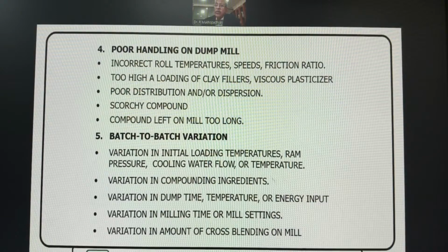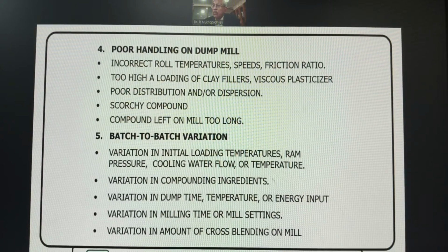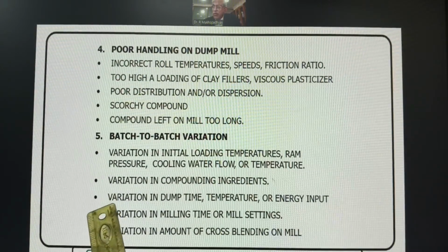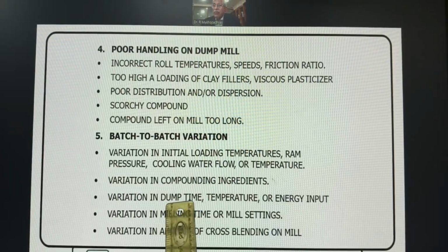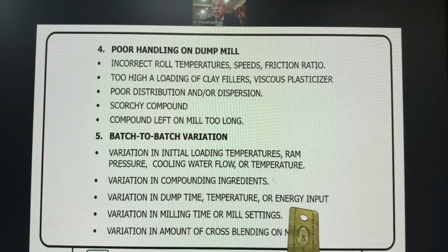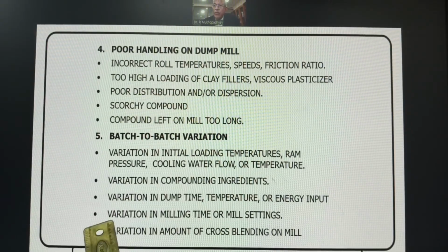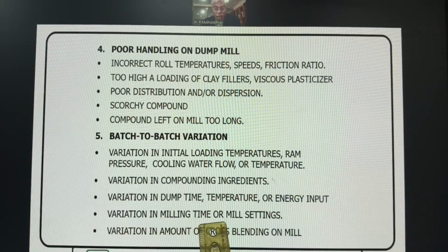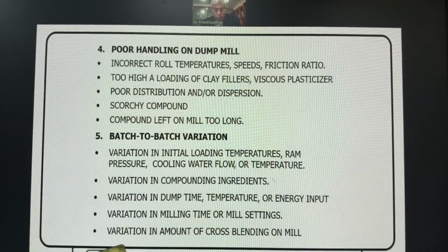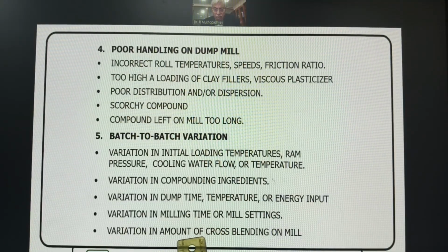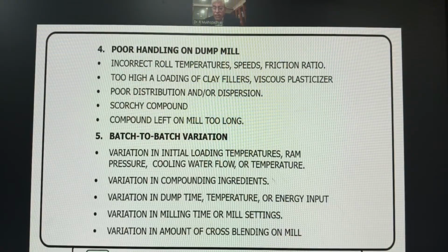If the chamber is very cold, initially you get loose carbon or unmixed compound. So unless the chamber temperature is a minimum of 110 to 120 centigrade, it is not sufficient. Then you add, so that there will be adherence between the metal surface and the polymers. Otherwise proper mixing will not be obtained.